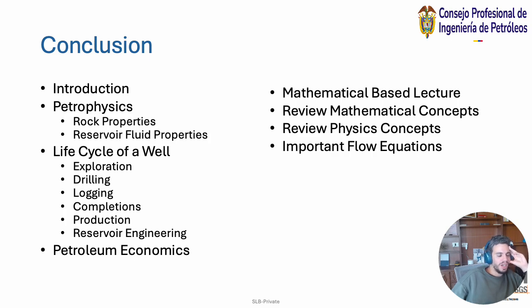And then we talked about multiple different flow equations, where we started out with the basic form of that equation, like Darcy's law. We took it to a radial front, where we're explaining the flow in terms of a radial movement to sort of come closer to the well-like structure. And then we took it a layer deeper and made it multi-phase. So we're accounting for the different fluids. And we did that with multiple different types of equations. And we finalized with some reservoir engineering principles and functions that are really important for characterizing water and oil.